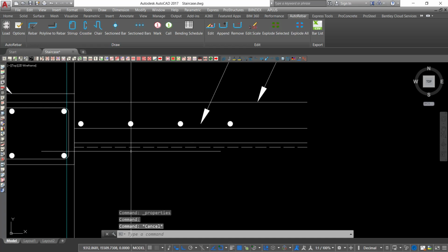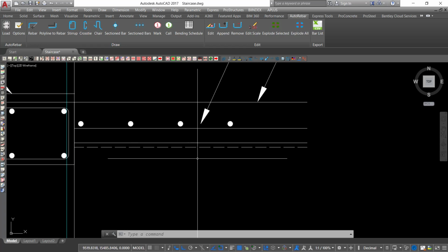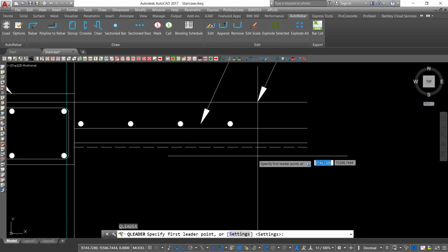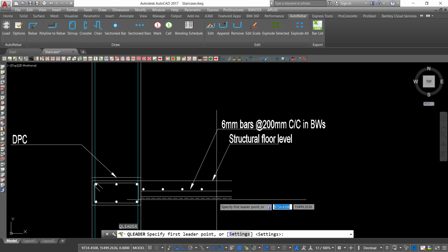So that will represent what we want to give out here. That will be a polythene. A polythene is another, it looks like a DPC, but it does the same job as a DPC. It also blocks the moisture from going through the floor. So we will mark this as LE. We'll point at it from this section here.